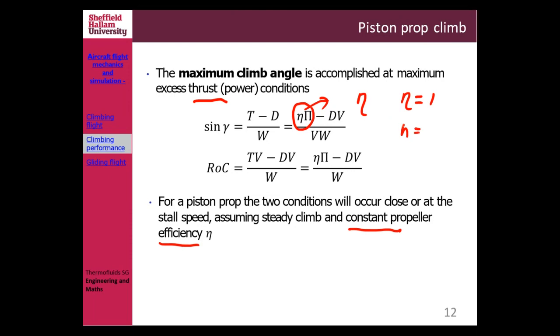Sometimes it's between 0.7 and 0.8, and sometimes the best is, I think, 0.9 or so. But anyway, the power that you get from your turboprop engine, which is the rotation of your shaft, is converted into thrust by your propeller. There will be some loss in there, which is compensated by the efficiency factor, the Greek symbol eta. Okay.